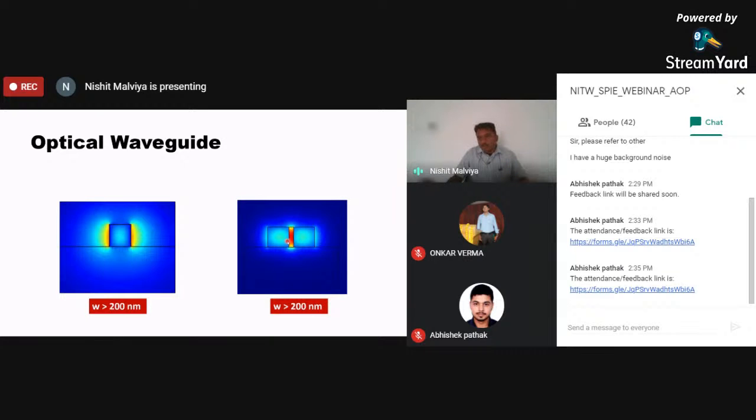When we talk about optical fiber, the light is confined in the high index region, but here the light is confined in this low index region. We have already discussed directional couplers in the textbook, but the size of that waveguide is very large, and the distance between two waveguides is on the order of micrometers. But here all things are in the 200 nanometer range. The height is 220 nanometers. Why 220 nanometers? Because most CMOS technology is a 220 nanometer technology. It is a very popular technology.